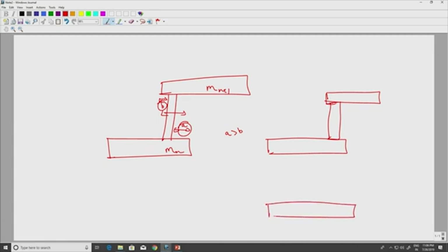So in the same architecture, what can happen is that because of misalignment, my metal layer has moved further away, and you might make a contact, but this is going to be a reliability issue.